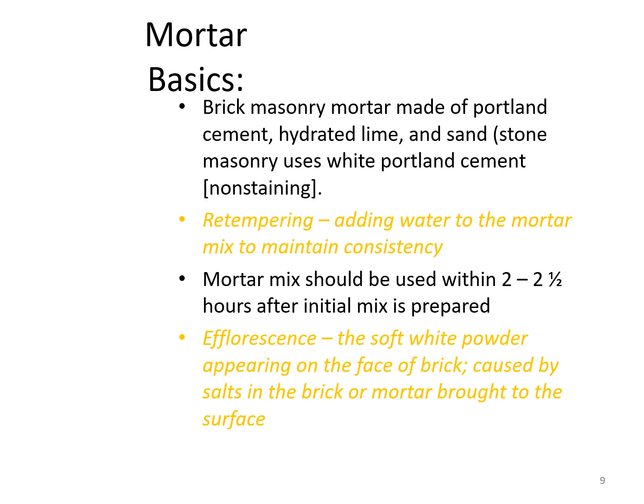But remember, the mortar mix should be used within 2 to 2.5 hours after the initial mix is prepared. If not, it should be thrown out.